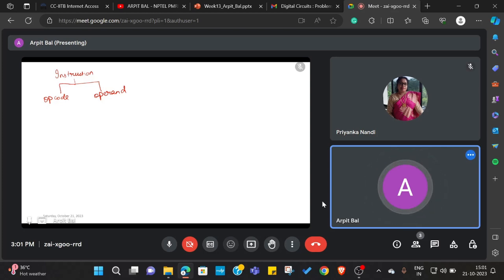Okay. So when any instruction is being executed, one thing that happens is opcode fetch, which by default takes 4 T states. In opcode fetch, the opcode present in the instruction is fetched, and the delay associated with it is 4 T states. The next thing is memory read or write, which takes 3 T states.